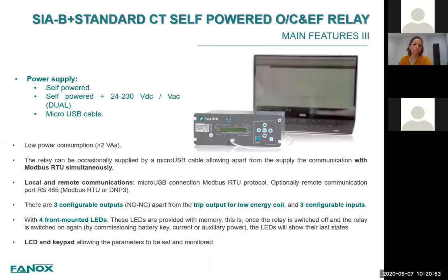In regards to the power supply, we can work as a pure self-powered relay, just with current. We can also use an external power supply, in this case a universal power supply from 24 to 230 AC/DC. Also the micro USB can be connected directly to the laptop or a standard power bank.